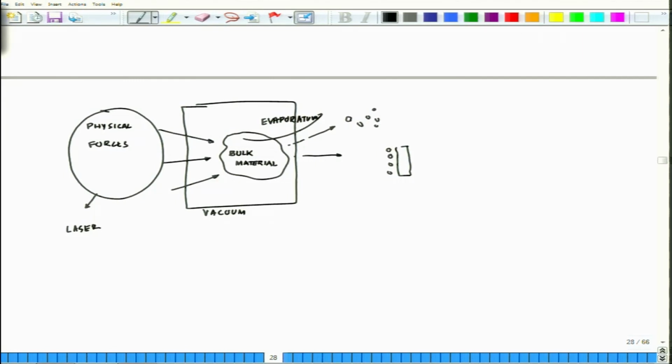So, in a normal laser ablation process, the laser can either be a continuous laser or a pulse laser. You could have a continuous source of laser or you can pulse it, depending on what kind of evaporation pattern you want. So, laser ablation offers a flexible approach in the production of micro and nanostructures of polymeric materials. So, if you have to work with polymers, we will be talking about that while talking about the applications. There will be a lot of such applications of laser assisted or laser ablation technique or pulse laser deposition techniques.